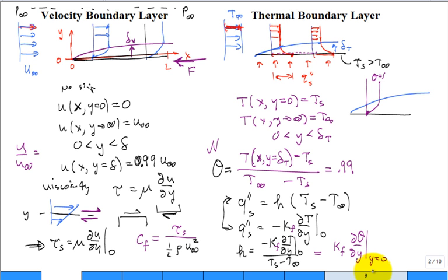All right. So if I go further down the plate, and I try to go, it's still going to go out to the same theta equal to 1 far away, but I have more distance to transition. Talk about the steepness of that profile. It's going to be very steep there, isn't it? It's going to be a rapid change in theta as I move away from the plate into the fluid.